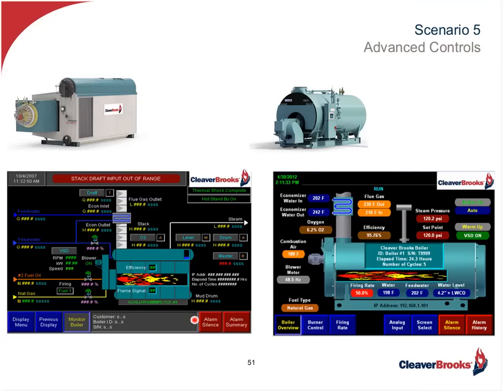And so these controls can help us get there, because what they do is they integrate my flame safeguard or my burner management system along with my combustion control system all in one common PLC platform. Bring them all together and then be able to accumulate the information so I can react early rather than reacting later with a trouble call and downtime.